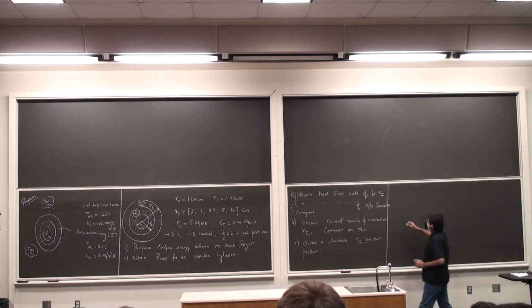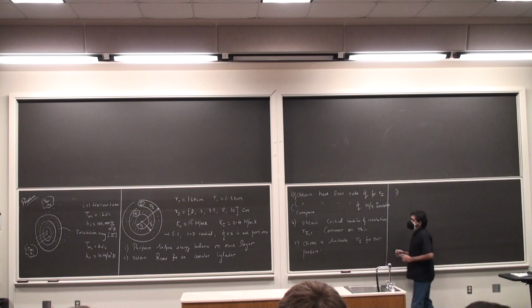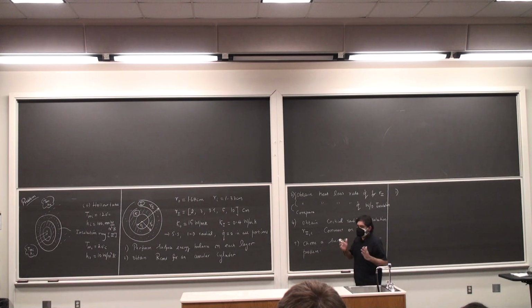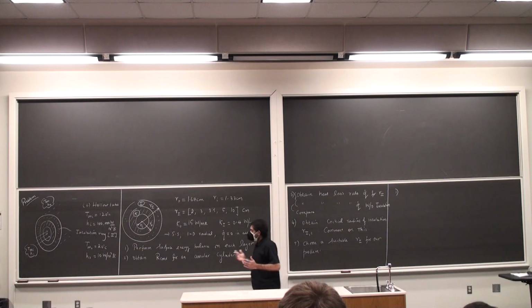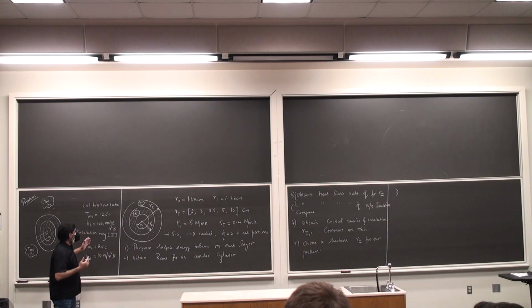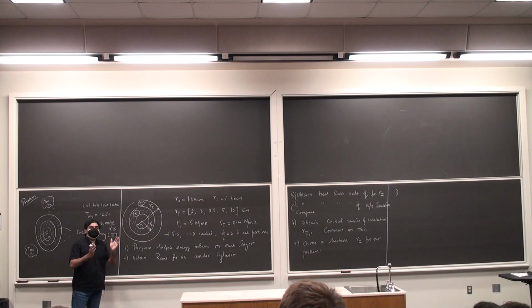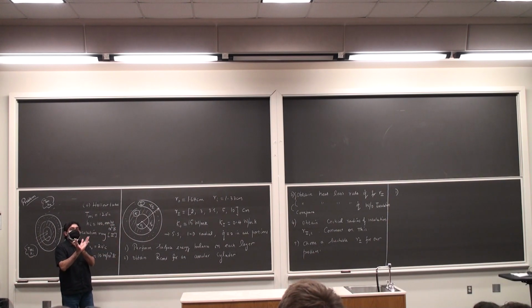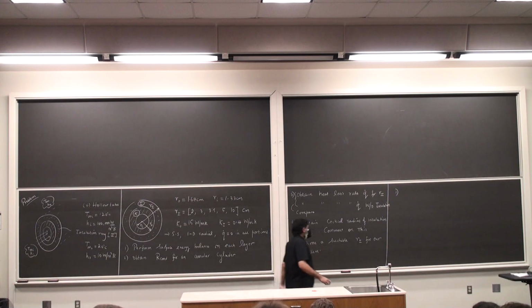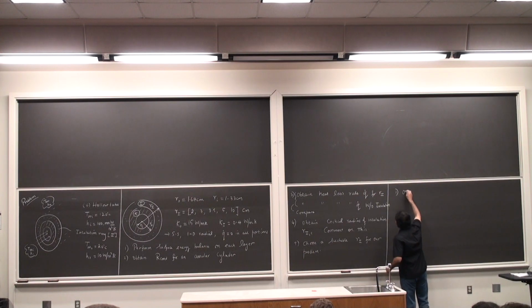So, first part of the problem. When you're doing the energy balance, the surface energy balance, obviously the generation rate is zero, the problem is at steady state, and it is not necessary to draw each of these as big circles. I can just draw a small sector, draw the control surfaces, and perform the energy balance there. Okay, as I'm going to show you now. So over a sector,